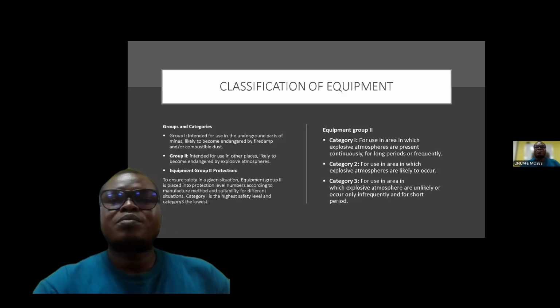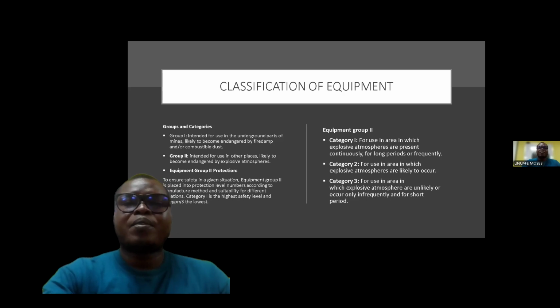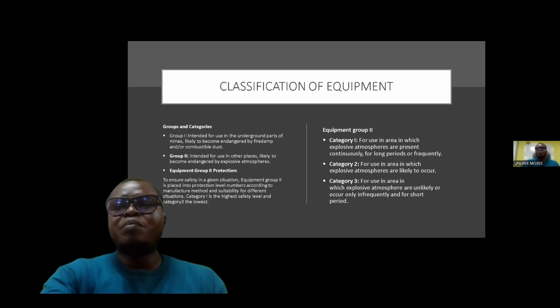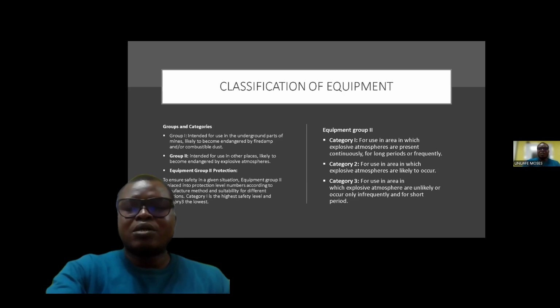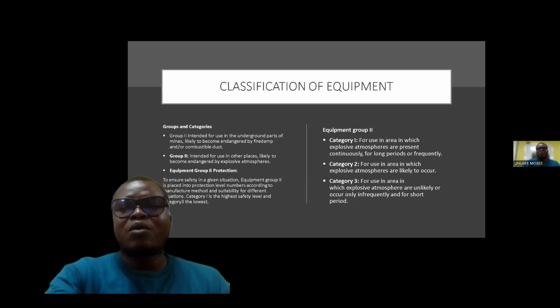And now, we want to look at an example. Let's take, for instance, installing an air conditioner in a Zone 2 area where a flammable gas may be present occasionally. You must select Group 2 and Category 1 equipment. Remember that the selection of your Group 2 and Category 1 equipment is on the nameplate of the equipment, which is tagged already by the designer or the manufacturer.